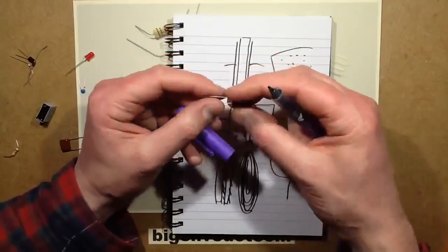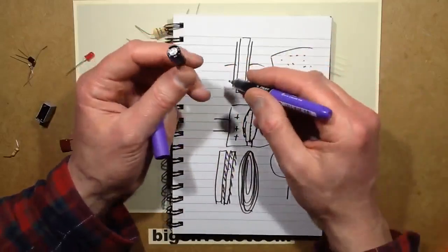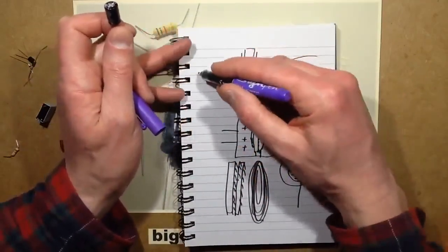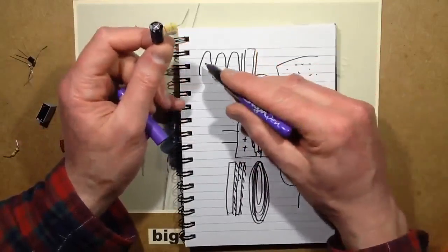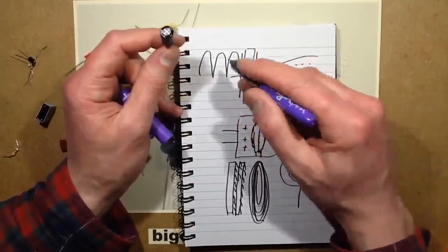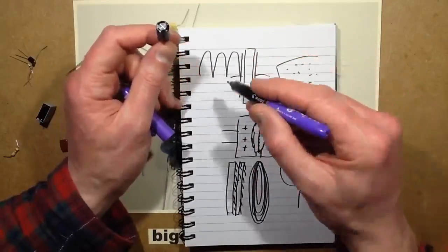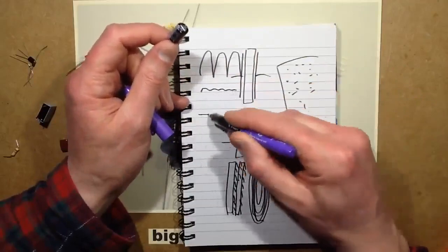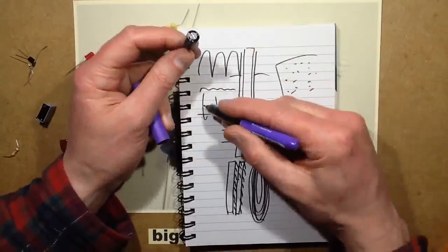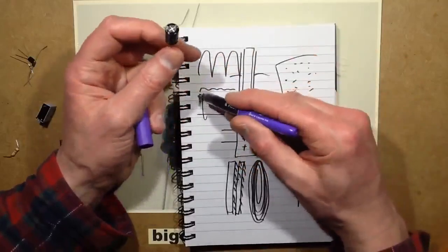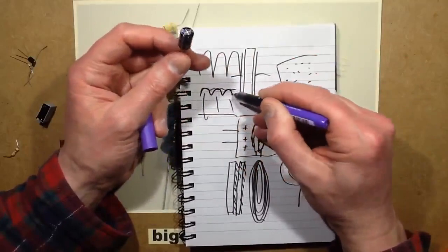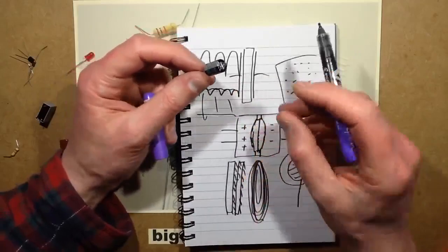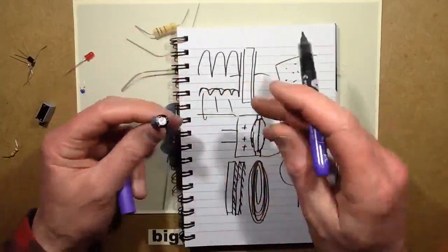When you get the large values like this, they're usually used to smooth ripples. So say for instance the output from the mains was rectified, and you had a big peaky AC full wave rectified waveform, which is like the two sides of a sine wave. Then by putting this across that, it reduces it to a very slight ripple and a nice smooth DC voltage. And as that capacitor dries out over time, that ripple will get bigger, and it ultimately starts causing problems when it dips down so low that the electronics can't sustain normal operation. And that's when you have to change capacitors.